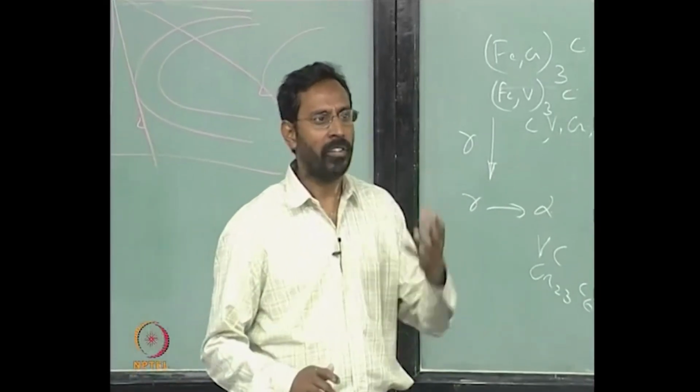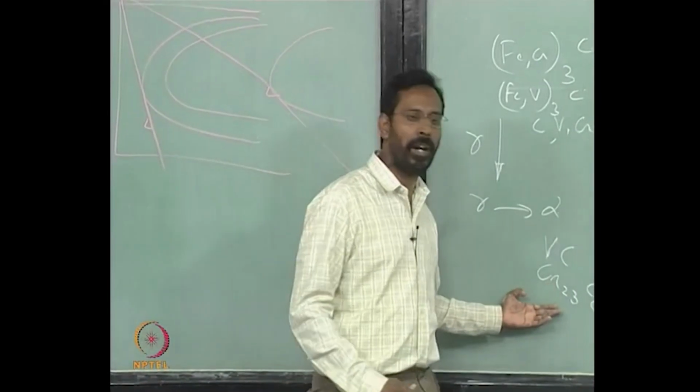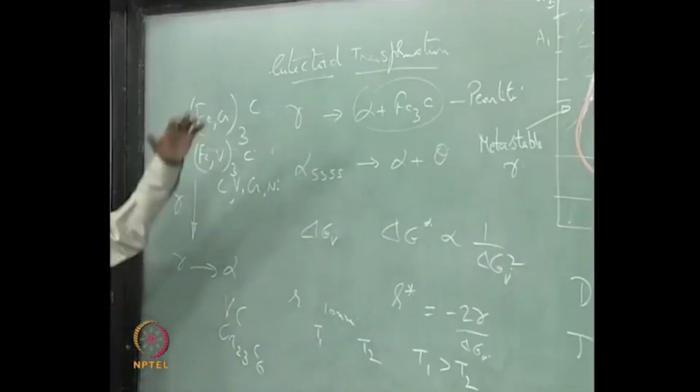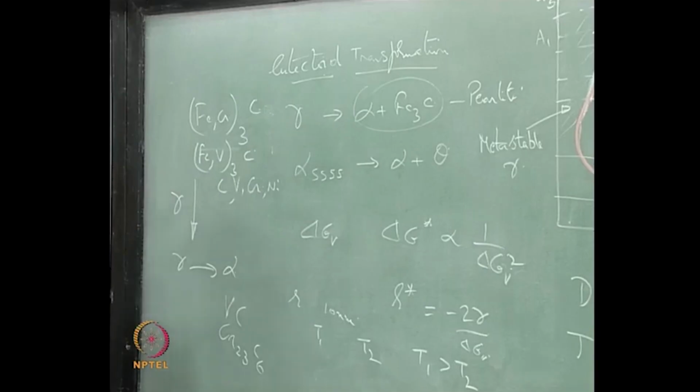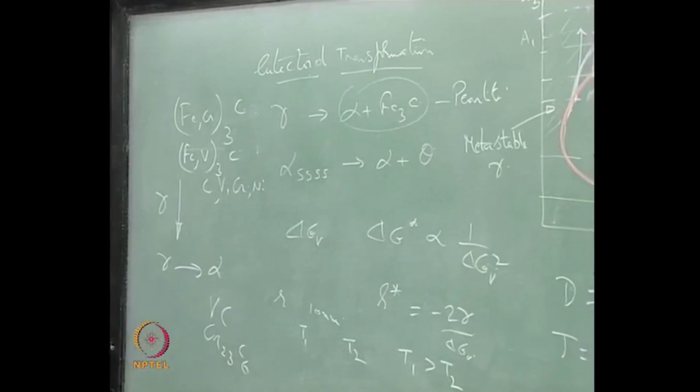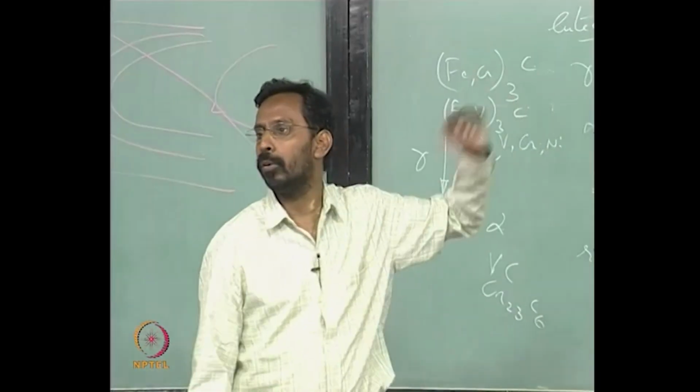So, the higher, the stronger the carbide. That is why chromium carbide can dissolve at a much lower temperature. So, if you have chromium inside the alloy, there is no problem, 900 degrees is good enough. But if you add vanadium, niobium, titanium, tungsten, the more you add molybdenum, all these elements, the moment you add, you need to go to a higher temperature.